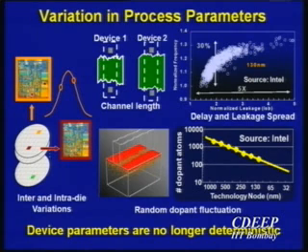And if you look at the end of it, if I look at 130 nanometer technology, this is a slide that I borrowed from Intel, showing a plot of frequency versus leakage. A lower threshold voltage really means a faster circuit, and a higher threshold voltage really means a slower circuit. So there is a good amount of variation in this 130 nanometer technology. And when I say a good amount, about 5x difference in leakage versus about 30% difference in frequency.